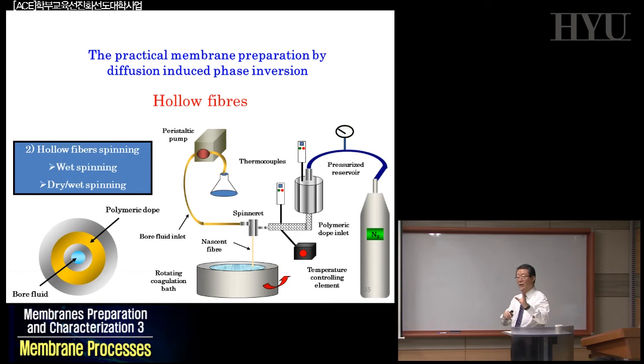You can have dual layer hollow fiber systems, where we have 2 polymers cast together using triple jackets instead of double jackets, double spinnerets. So by designing specific spinnerets, you will be able to make just a hollow fiber with the same membrane, same polymer, or you can have a dual layer hollow fiber system.